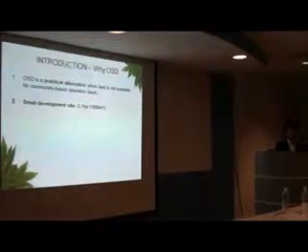We look at why we choose OSD. OSD is a practical alternative when the land is not available for a community-based detention basin, or the development is very small. It's only 0.1 hectare. In the submission list, it's written there, if the development is equal to or less than 0.1, we can use OSD. If larger than 0.1 hectare, we need to use a detention pond. But case by case, these are the general rules written in the submission list.